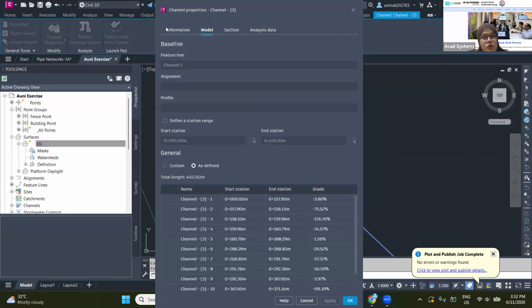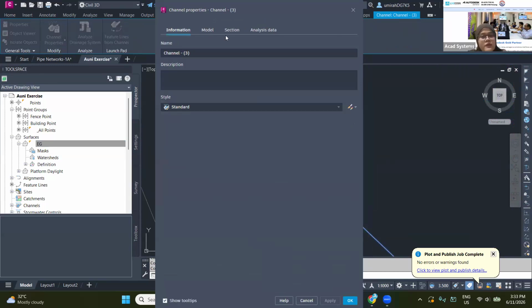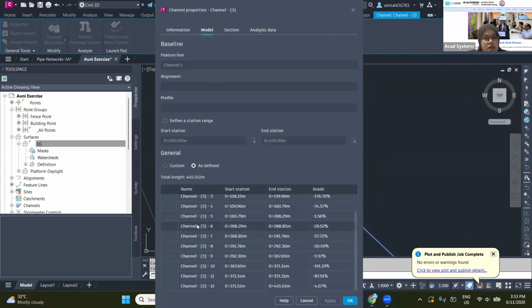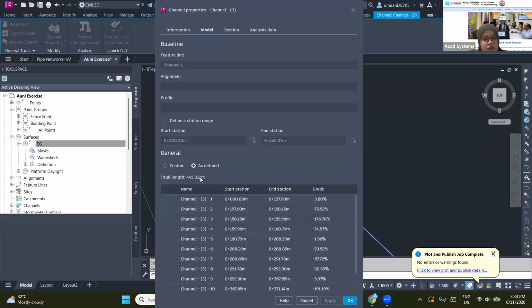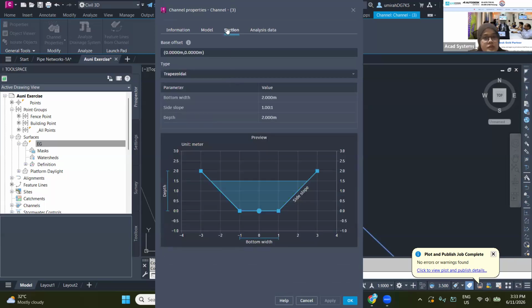This is just a quick view. I have my channel name, the style, the model, the channel length, the general setting, and so on. You can see here. And to apply that subassembly inside this channel design, you can just go here in the section tab.